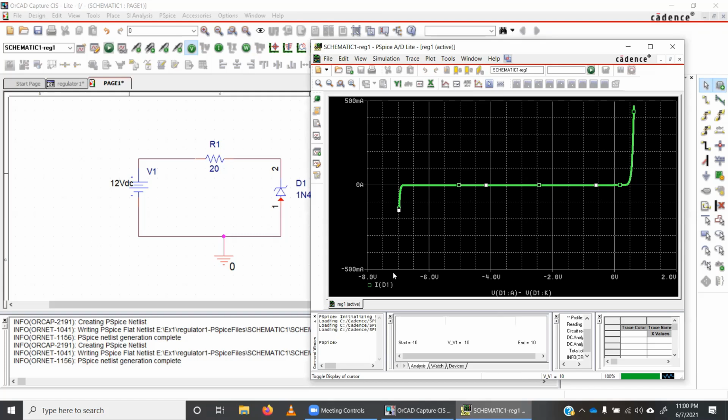So I change it from roughly about 7 to 2 volts, and the current. Actually the voltage is basically limited to this range. Even if I try to increase the positive or negative voltage, the rest will remain in the safety resistor. So you can see that. So here this is 0, and at about 0.65 you get this current conducting section. And also when you reverse bias it, at about 6, and at 7 actually, you are getting this.